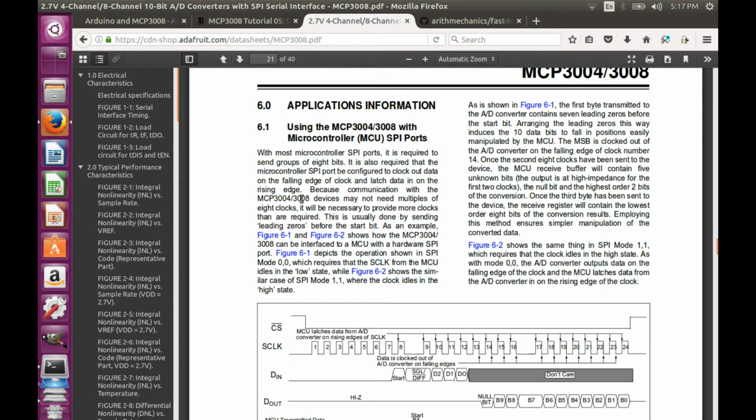On the downside, you have to use buffering to provide the signal to the ADC, because with sampling that fast, the precision can only be achieved by using low impedance sources. So you have to look up how to create a voltage follower and make sure that you minimize the noise in the system coming from the digital side.